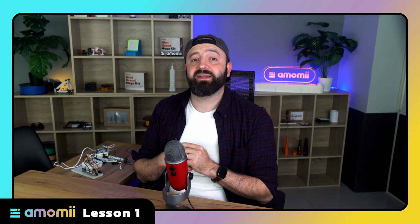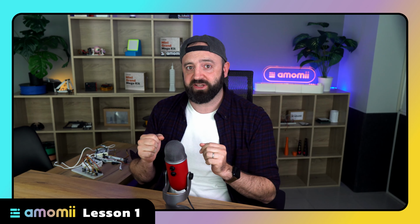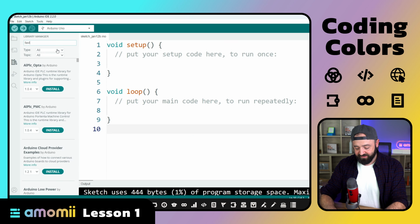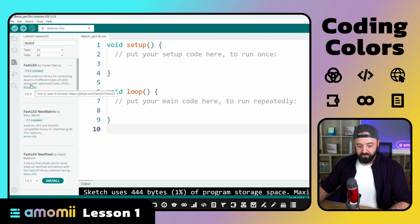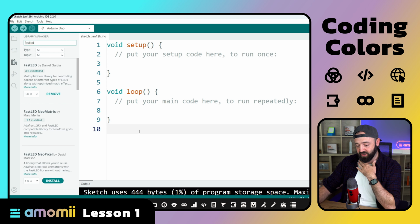A coding library is basically pre-written code that you can access, making complex tasks much easier. We'll be using the FastLED library to help us code our pixels. From the library manager, type in FastLED. And the first one that comes up will be the FastLED library by Daniel Garcia. In my case, it says remove. That's because I already have it installed. For you, it will probably say install. Click the install button and you should have the library ready to use.